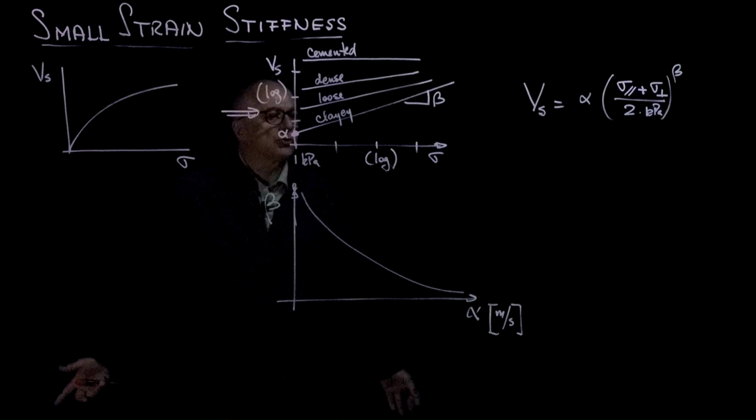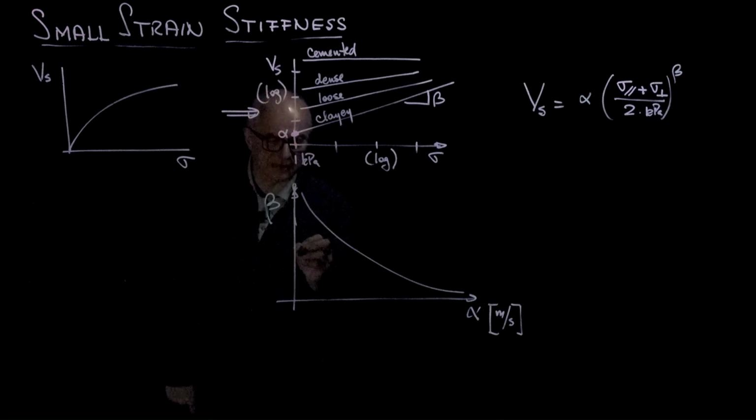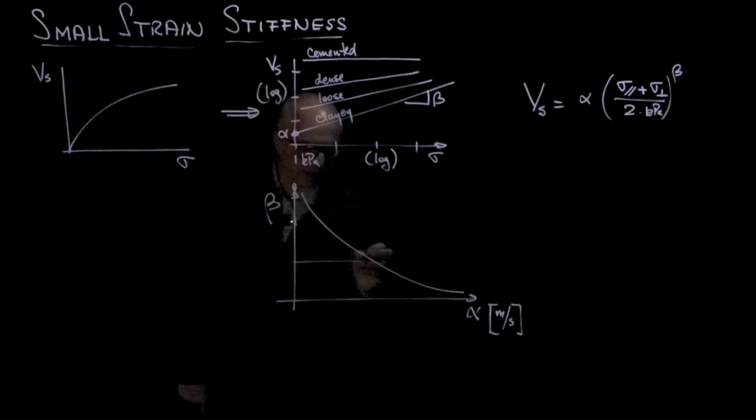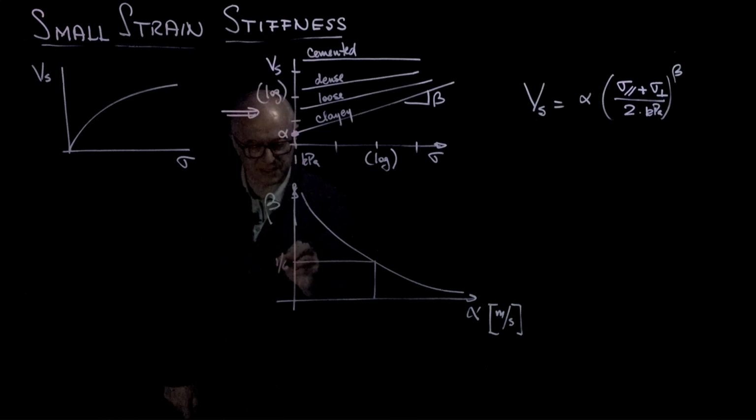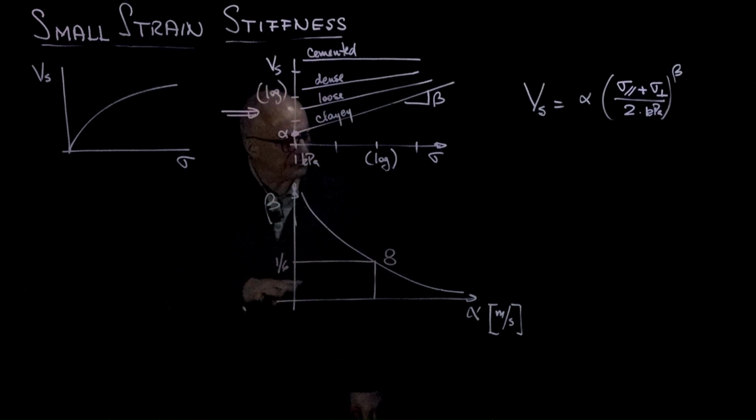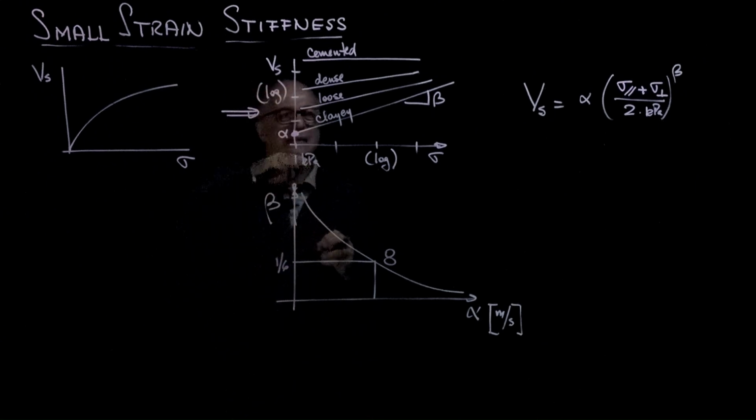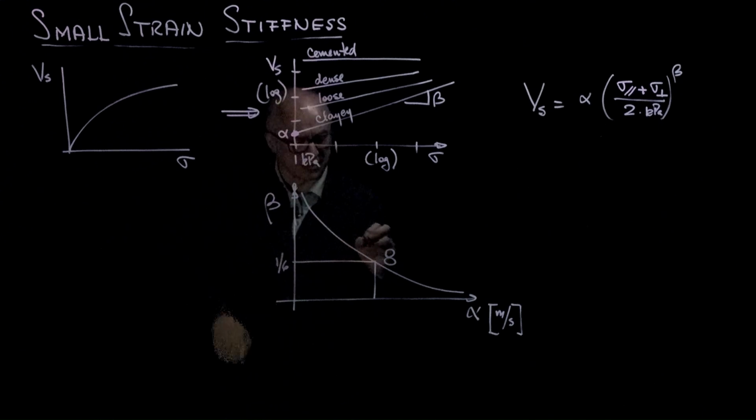If we were to plot here, where does a Hertzian contact fit? The Hertzian contact, remember, for velocity is 1/3 times 1/2, so this will be at 1/6, and so this is a Hertzian contact. Now, if particles become rougher, the contact becomes softer, and then it's more sensitive to state of stress.